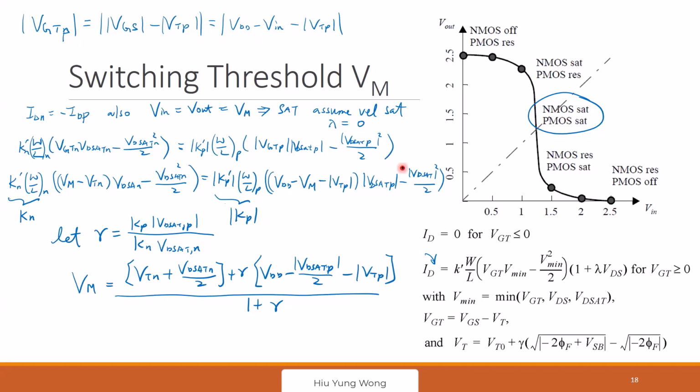Professor, here we are assuming that the VDD is 2.5 and then VIN is around 2.5. So what if VDD is 5 volts and I still restrict my input to 2 volts? No, to find VTN, it means that you switch the VIN from 0 to VDD. You cannot just say, for example, you restrict it to 1 volt, but that is not the VTC. You cannot just go here and then stop, because we need to sweep all the way to VDD for a VTC. Make sense?